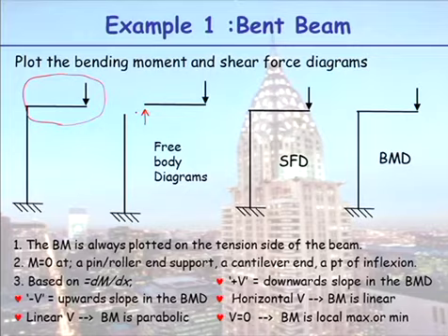To give me equilibrium, I'm expecting you all to be going, okay, that's going clockwise. So to oppose that, the internal bending moment here must be anti-clockwise. Now, remember I told you about sign convention. If I draw it anti-clockwise on one side, I draw it clockwise on the other. So when you put it together, it's in equilibrium. If I have drawn my moment here anti-clockwise, that means the moment on my vertical leg will be clockwise.